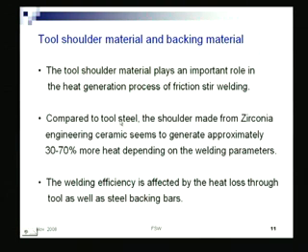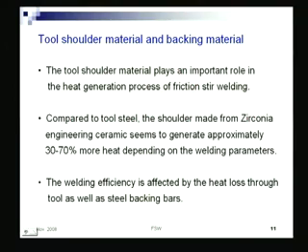What is this tool steel? Tool steel is nothing but the type of steel from which you generally make lathe machine tool bits, drill bits, all that. That means they have sufficient strength, and also they can withstand a sufficiently high temperature and still maintain the required strength.